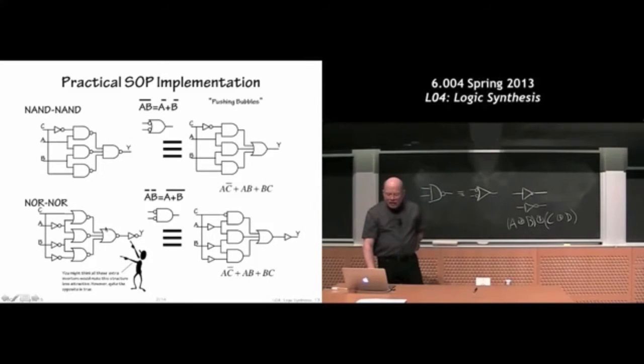Yeah, so the idea here is that, notice that to just charge and discharge this output node in this diagram, I have all the FETs, in this case the pull-down chain for the NAND gate. So all that current has to flow through this little stack of 3 FETs. Here, inverters can be made very fast, because there's only a single FET in the pull-down chain and a single FET in the pull-up chain. And in fact, I can make them wide FETs. And so what I have is the ability to drive very heavily loaded signals with a lot of capacitance. I can make them switch faster.